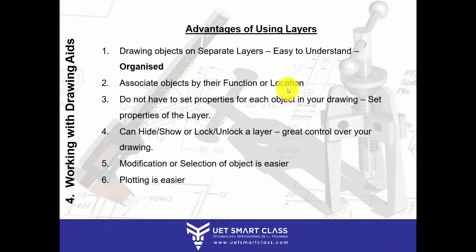You can set the layer properties and drawing properties with such color codings or standard names that everyone can read. Like we know a brick wall is of red color, so we can give a red color to a wall layer.